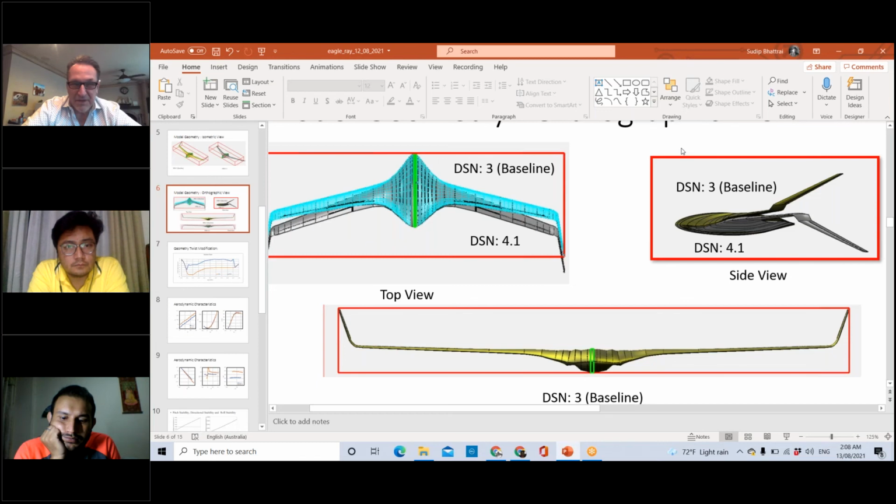It's doing the blade element model, the airfoil stack model with the nonlinearities. If I see it spin in X-Plane, it's probably going to spin if we stall it right now. So what I'll be really interested in is to see how the new incidences on the wing have affected the stall pattern from tip to root.